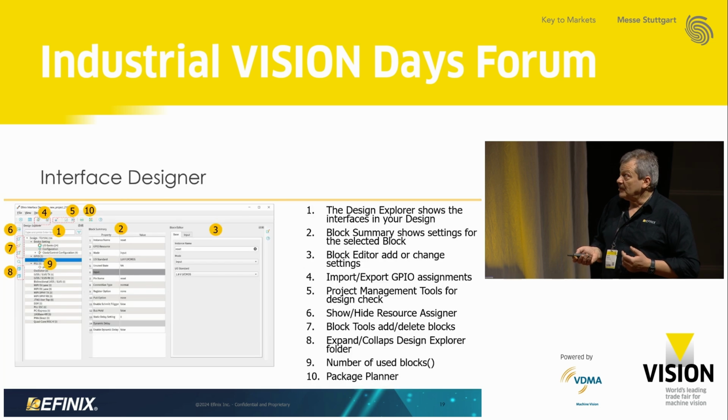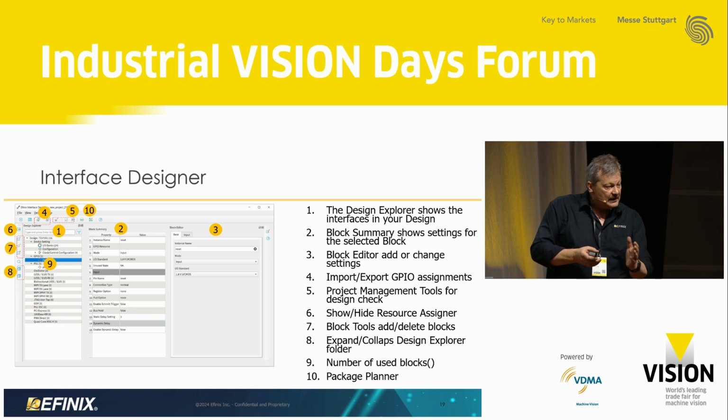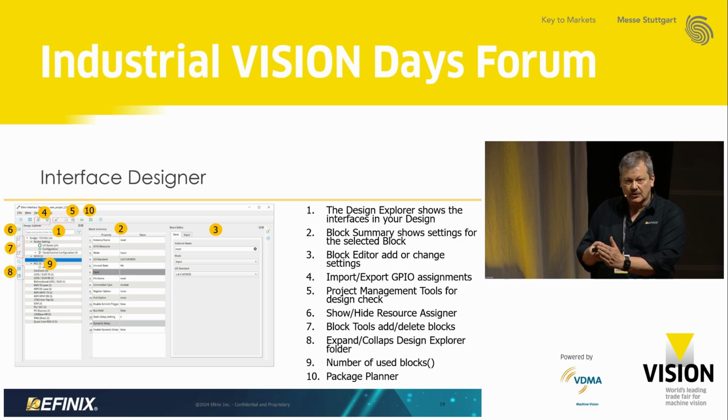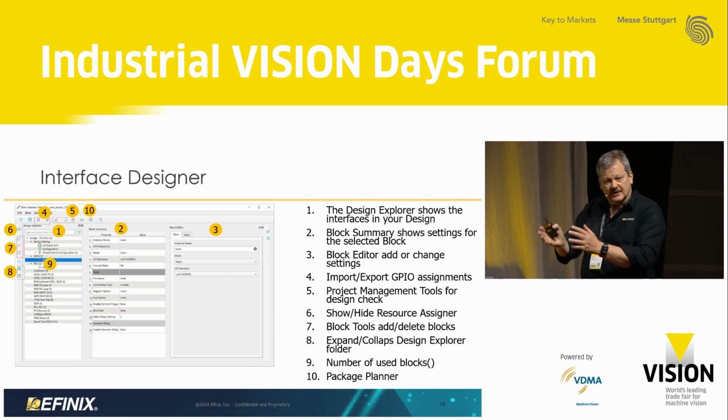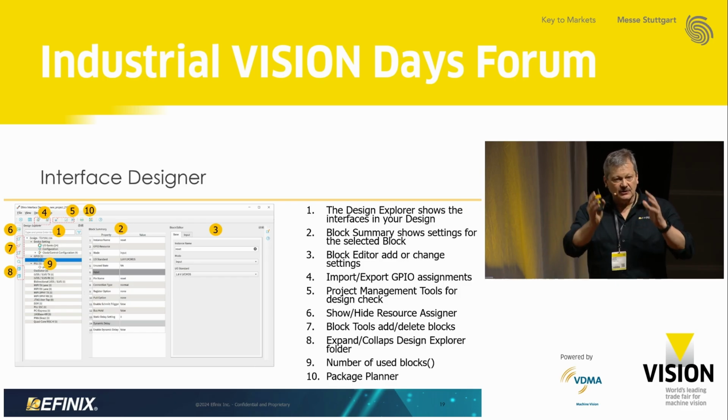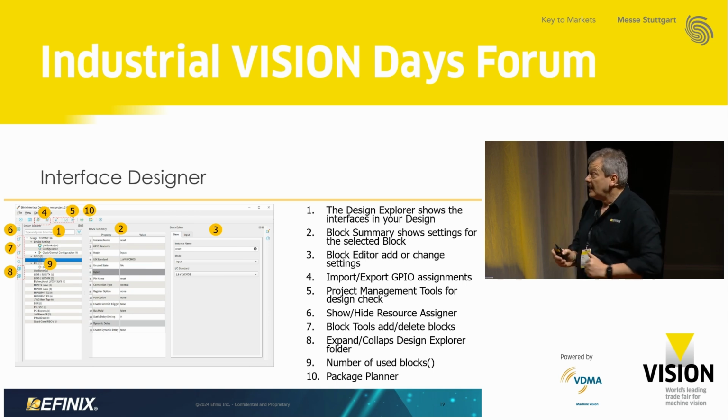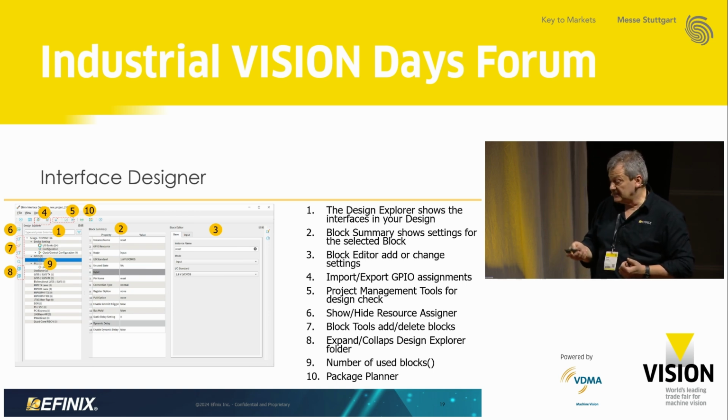Then sure, we have a floor plan viewer and the interface designer. This is a bit of a different approach compared to the other FPGA vendors. All the IP cores we are providing are in the interface designer. So if you have a PLL and would like to generate 3 clocks, you generate the 3 clocks in the interface designer, clock 1, 2, 3, and then the connection is done in the entity top module, clock 1, 2, 3. Done. But then you have all your design in the core design, and everything that is vendor specific for Efinix is in the interface designer.